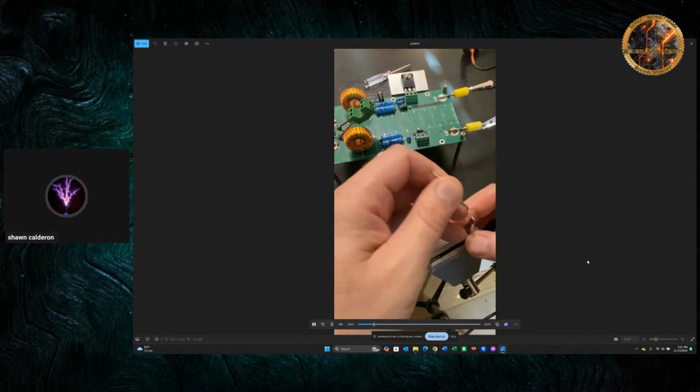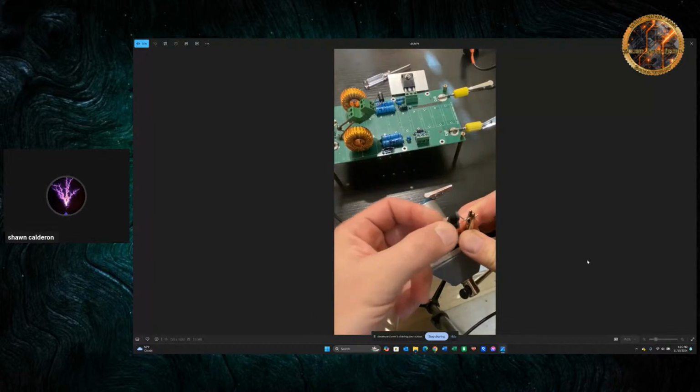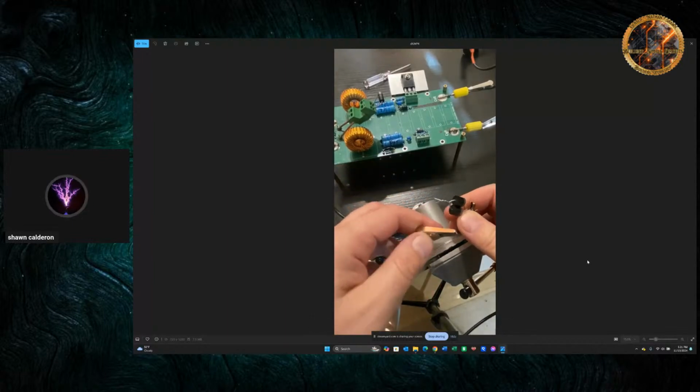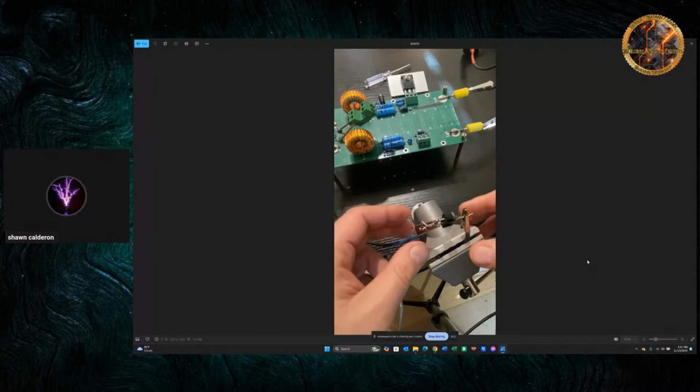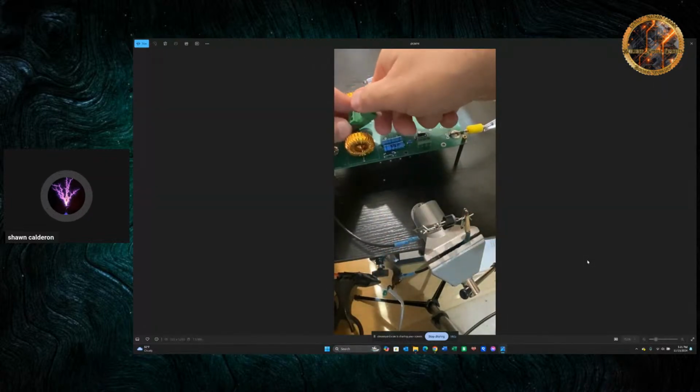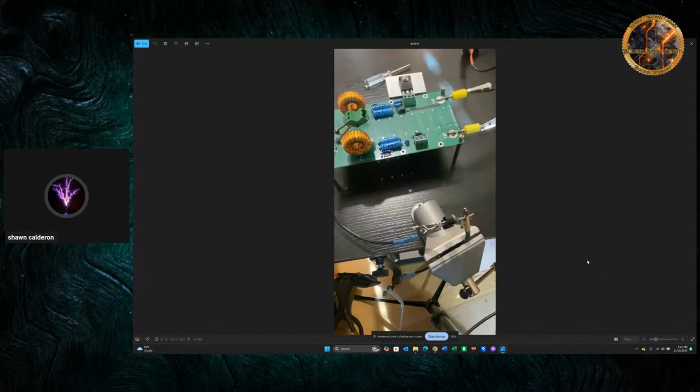Now, if it isn't, okay, so we're going to put those diodes back because they're good. And then we're going to go to the next culprit, the very next culprit. And you'll be surprised to find out it's not the MOSFETs, it's this diode. Now, it's kind of funny because you can see I put a green terminal connector here to plug and unplug that diode, because that diode is the next guy that'll get you upset and ruin your day. And so we'll remove that diode to test it.